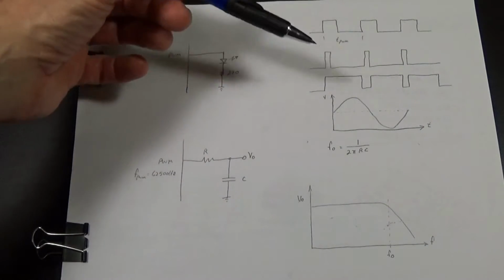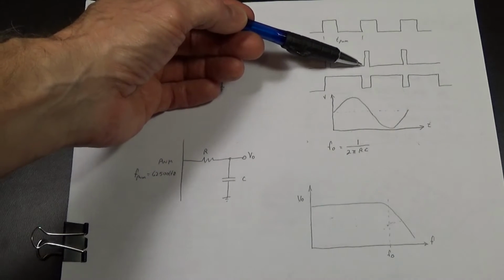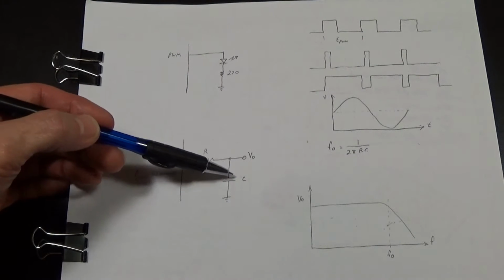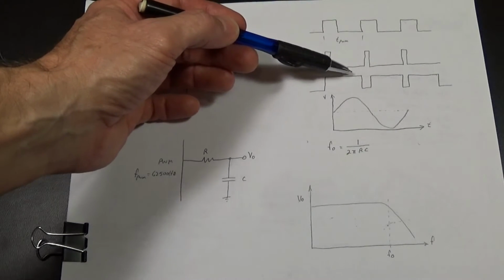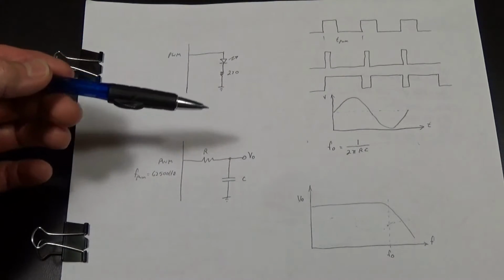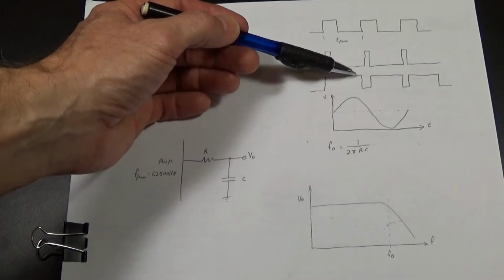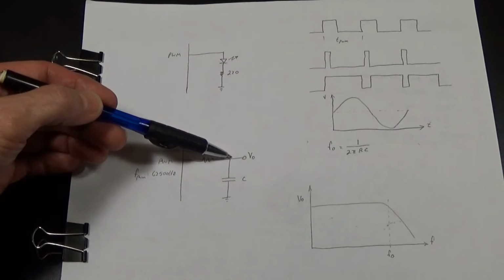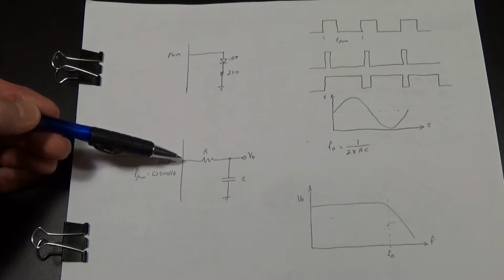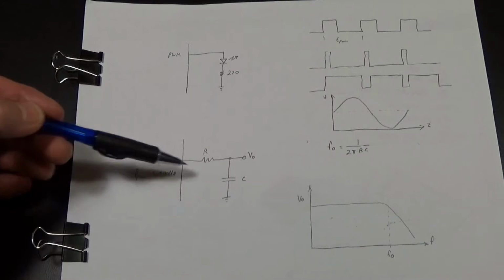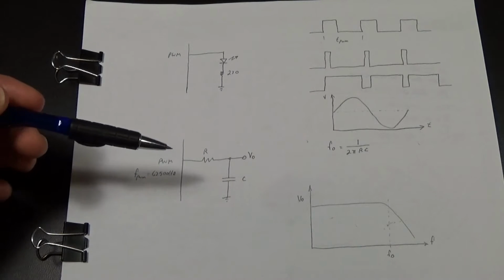signal. And so in this case, for example, the on time is very short and the off time is very long, and so the voltage coming out of here will be low. Conversely, here where the on time is much longer than the off time, the voltage will be high. And if the on time is 100% duty cycle and it's always on, then the output here will be the same as the voltage at this output of the microcontroller. And of course the lowest voltage it can reach is when the microcontroller voltage goes to 0. So that's essentially how it works.